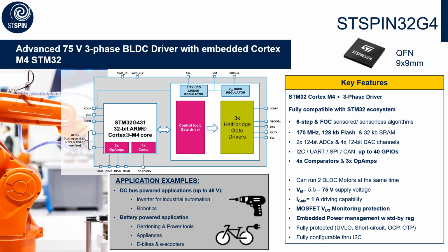It also has an improved power management. Here we're using a 3.3 volt LDO to supply the microcontroller, a programmable buck regulator which supplies the driving section, and an embedded standby regulator to have a faster startup time.